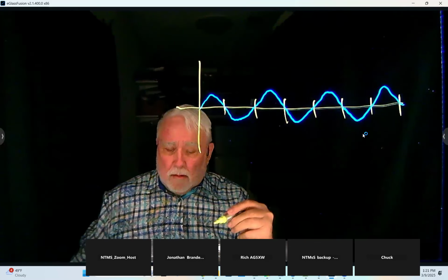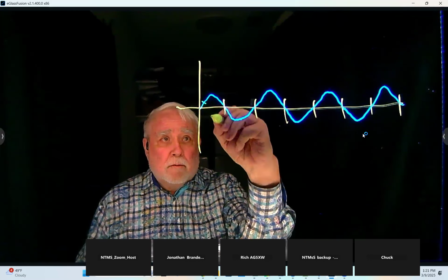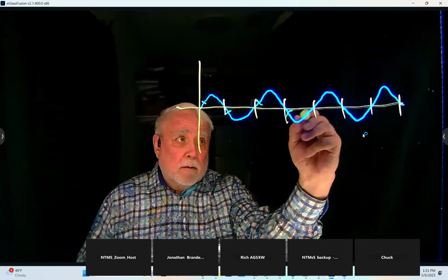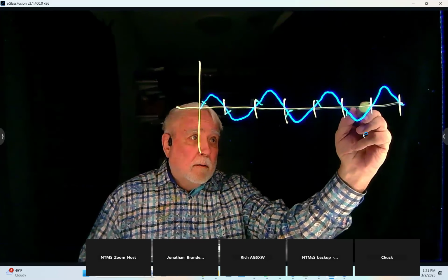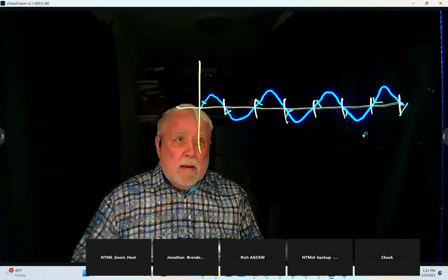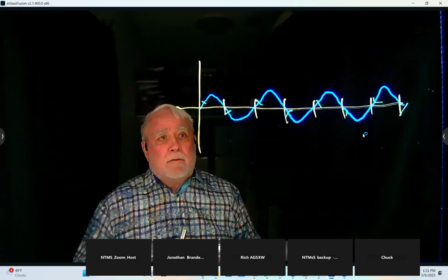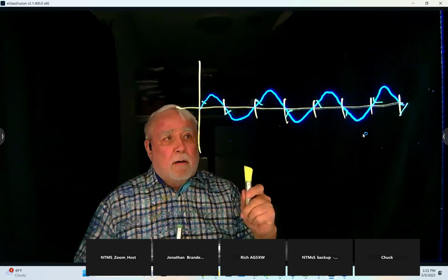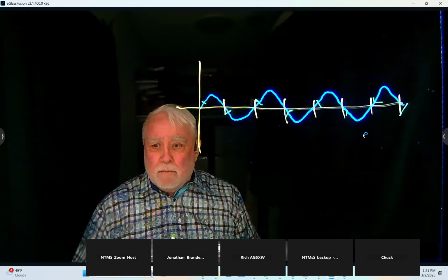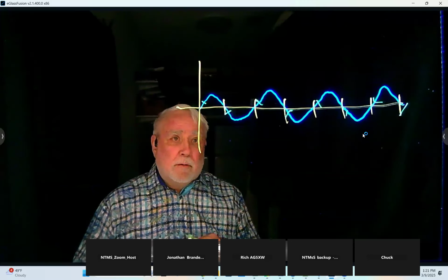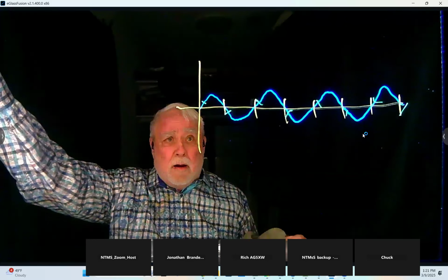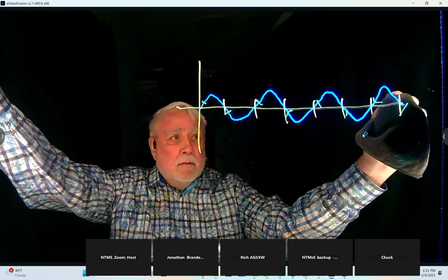And sampling at 2 times, if we're starting there, the next one will be there, next one will be there, next one will be there, and there. So there's no way you will get any other signal to match those sample spots except the one in blue until you go to a much higher frequency. And when you go to a much higher frequency, then there's a match, which is a different kind of problem because once again, you haven't got your sample rate high enough in that scenario.